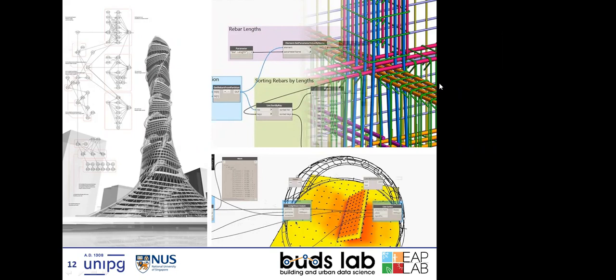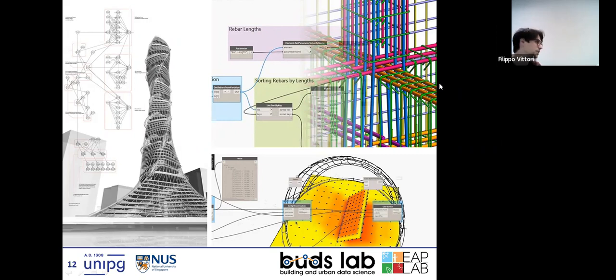Yes, everything. And of course, there are architects using Dynamo, because before, with Revit, you couldn't manage difficult shapes. Now it's possible because of Dynamo, since the families are quite restricted in their properties, so you couldn't create crazy shapes. They are similar, but within Rhino you don't have access to structural properties. You can input them, but there is no slot given by default. In Revit, it's very focused on buildings, the construction industry. You wouldn't design a car in Revit. You can, but you wouldn't. It would be silly, right?